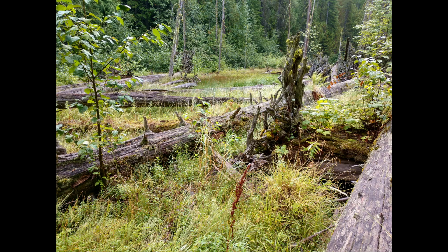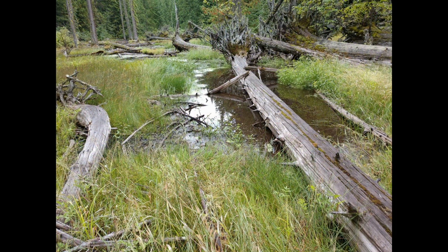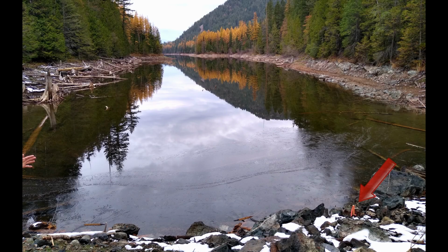We also took elevation readings on the ground immediately downstream of the dam in areas that had not been disturbed when the dam was built. We drove a stake in the ground to serve as a benchmark for construction. The elevation on top of the stake would be the same elevation in which Goodeve Creek would begin flowing over the dam after it was removed.